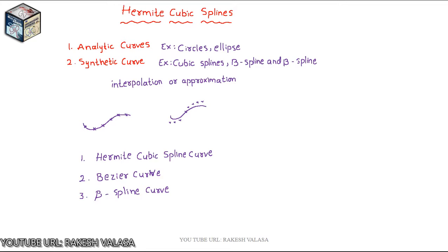Splines draw their name from the traditional draftsman tool called French curves or splines. The Hermite form of a cubic spline is determined by defining positions and tangent vectors at the data points. The parametric cubic spline curve, also called cubic spline for short, connects two data endpoints and utilizes a cubic equation.